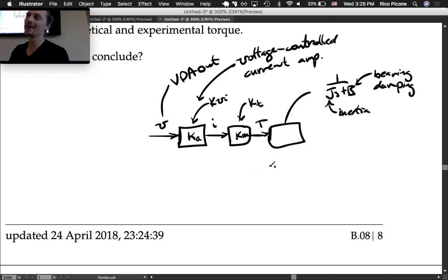So it's saying independent of what the circuit is, for instance the resistance in the windings, regardless of that, this amplifier should be supplying whatever current it says it'll supply, up to a certain voltage max. That's why for motor control, people like using these voltage-controlled current amplifiers, because it's a little easier to model.